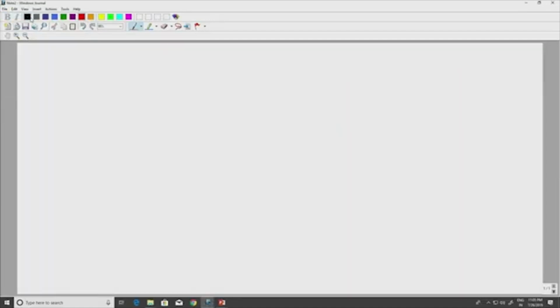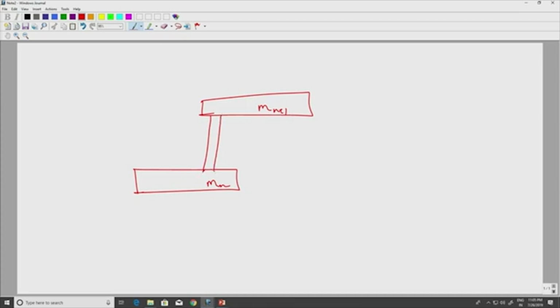And the other important thing I would like to highlight here is how you are going to address the alignment issue. I have metal N, and then we have metal N plus 1. Here we have one interconnect, but then the distance to the edge, let's say this is A and B. A is definitely larger than B. That means for any misalignment, left or right, connecting to M1 is highly tolerant compared to B, in whatever direction.